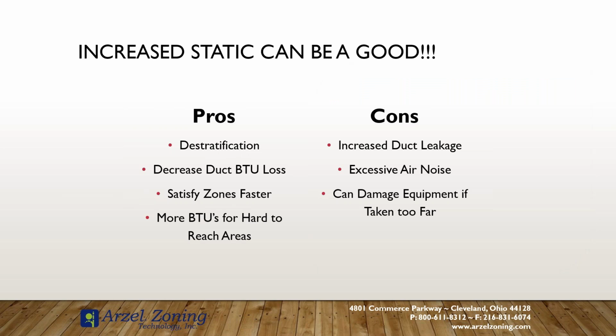But increased static can be a good thing. It really can be our friend. When we increase our static, we get better destratification. We can decrease duct BTU loss because the air is moving through that duct faster. It spends less time in contact with the duct surface area itself, so it sheds fewer BTUs. So more BTUs make it into the zones rather than staying in the ductwork itself. We can satisfy those zones more quickly because we're targeting the area that needs that BTU gain or that cooling the most. And when we target that area, we satisfy it faster and we make it more comfortable because we're